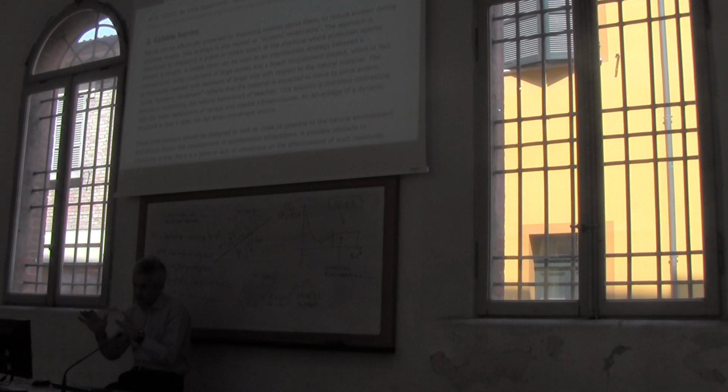Remind the difference between the berm and the dune. The berm is formed at the end of wave run-up. It is usually developing during the good weather season. It's typically eroded during storms. In the berm you don't have vegetation. You have sediments transported by the waves, so it's something that elevates a little bit over the beach. Behind the berm you can have the runnel, which is like a small channel with some salt water.